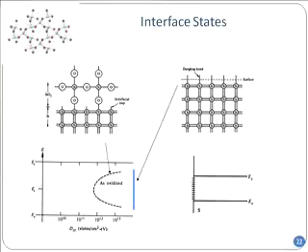And therefore, when you oxidize, it reduces the density to 10 to the power 12, right? Because many of them have been taken care of by the oxygen, but still you would be dead with 10 to the power 12 per centimeter squared of interface traps. So that is the story of the 1960s, that they then spent a huge amount of time to push this interface defect density down to 10 to the power 10 nowadays.